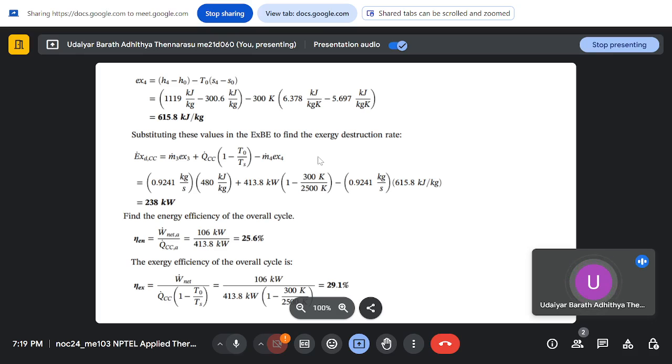But doing so here actually dropped your efficiency, because the turbine and compressor are not fully 100% efficient in the actual case, and that dropped your efficiency of the cycle significantly, and that could be overcome by employing a regenerator. So that is a bigger takeaway here.